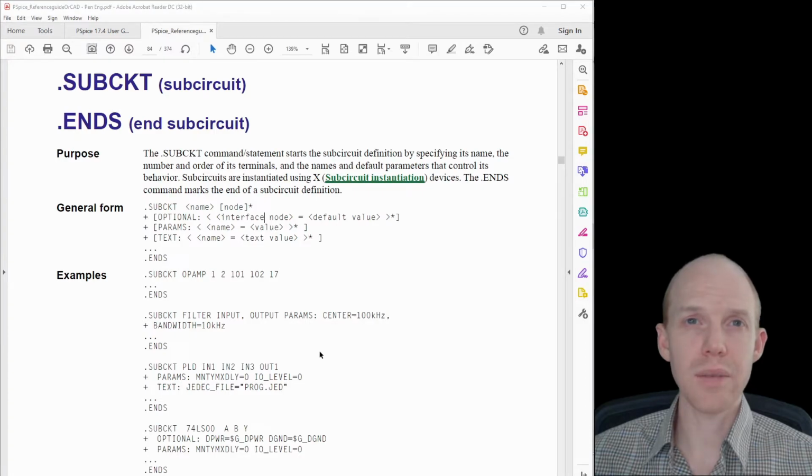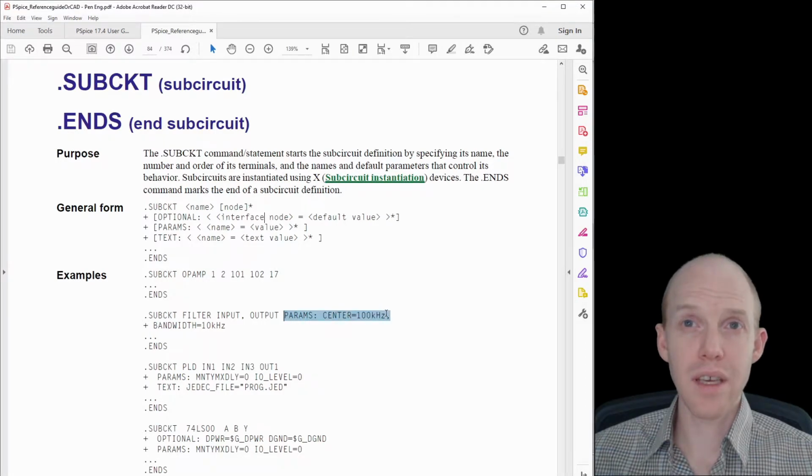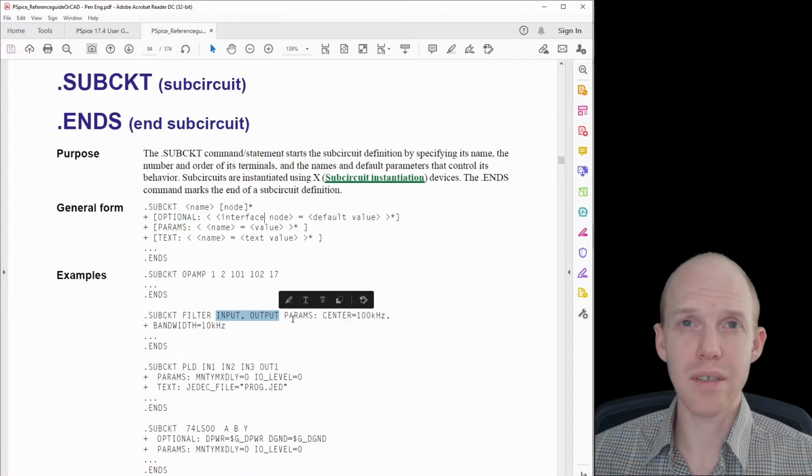And the other cool thing about subcircuits is you can put this params thing on the top here. So you write subcircuit and then the name of it, and then you have the lines coming in and out of the subcircuit, and then params, colon, and a list of parameters that go name equals value.